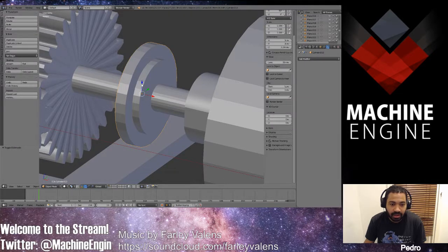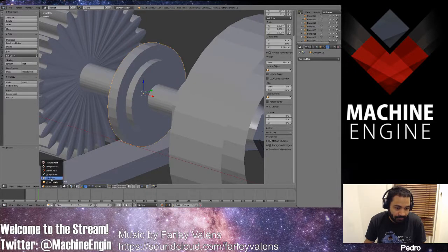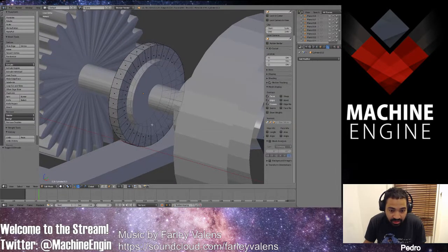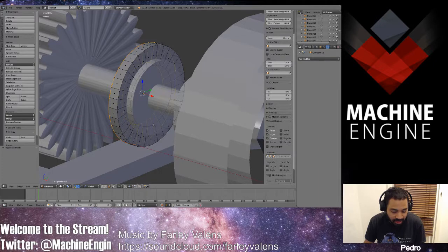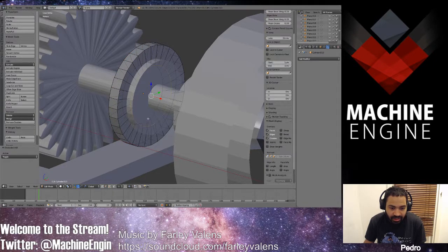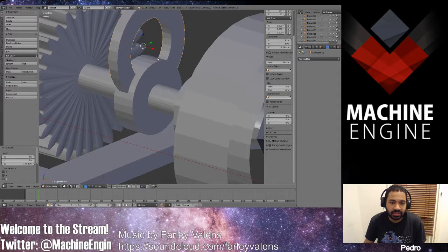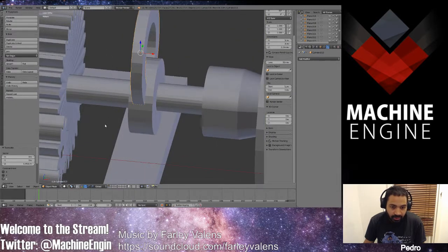Now we go back here and check it out. Oh, we got a hole. Yeah, okay, cool. Now I do this. This is a nice trick I always like to do. Make sure you put it on select lines, and then it's this one, and then press W, and then bridge edge loops. There we go. Now what did we just make? We just made a cylinder with a hole. Real easy.